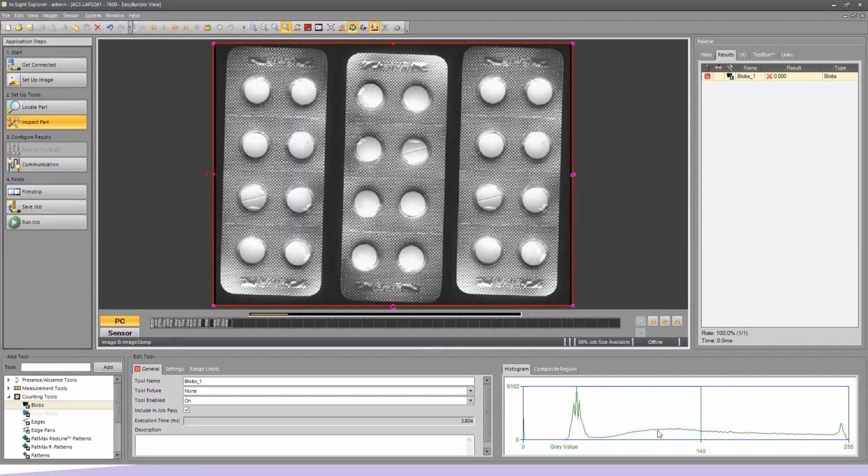Now, between all of this, there's a whole lot of other pixels of all sorts of different colors on the grayscale. That's going to be all these different reflective areas and textures and shadows that are actually part of this texturized aluminum backing that we have on the back side of this pill pack. That's what's really confusing us, because a blob is a group of pixels that are the same color that are touching. Well, there's so many different colors and so many different variations that we really can't discern the blobs that we want to discern with it.